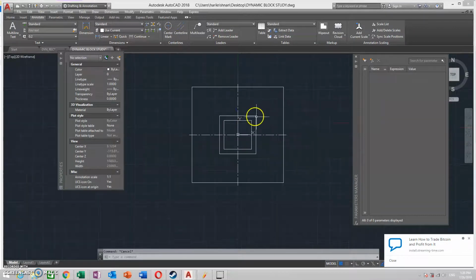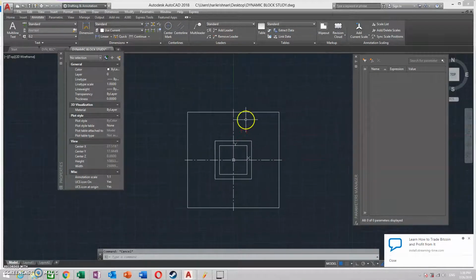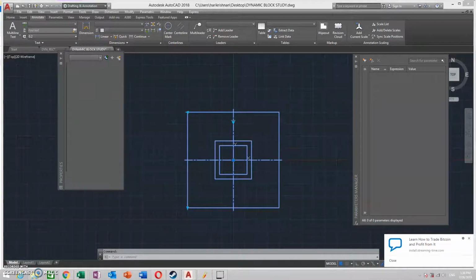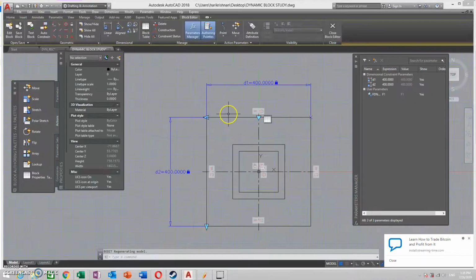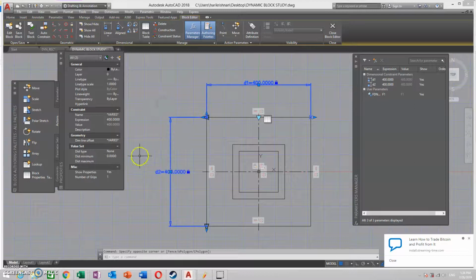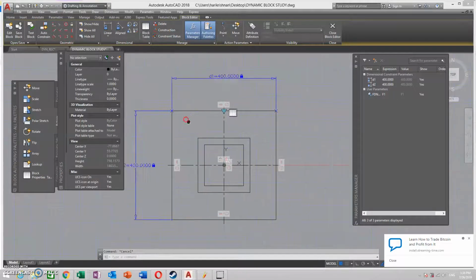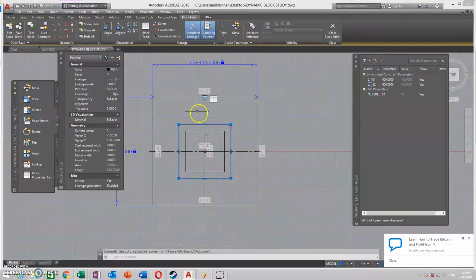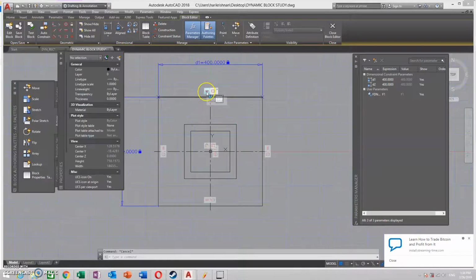Okay, now we need to change the footing, then the base plate. So now we'll go inside the block again. Okay, if you don't want to use the grip for this one, select both of the objects, then here you can see the grips. If you want 1, 2, 0, these 3 options are there. If you keep 2, both sides you can stretch. If you want one side, 1. 0 means no grips. Okay, now we need to go for the footing. So repeat the same constraints whatever you did for this. You can give vertical, then horizontal, and the symmetric.